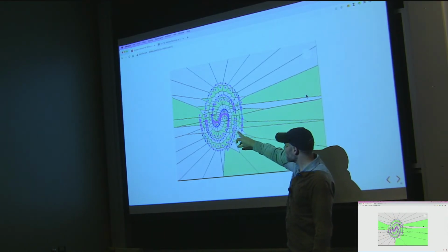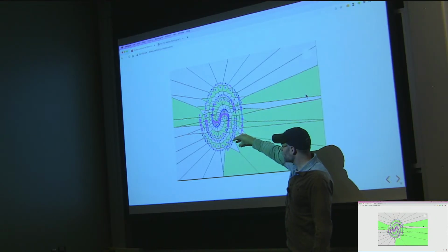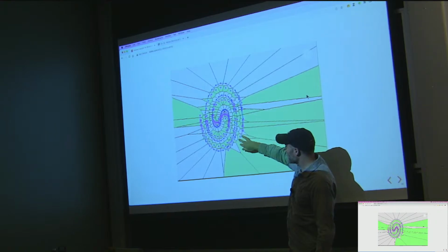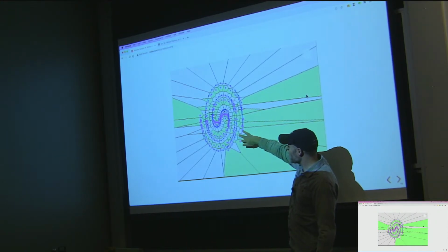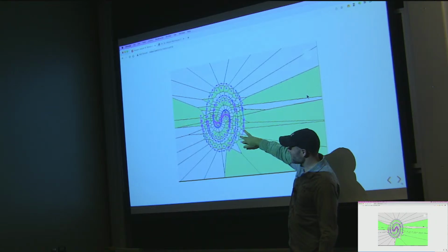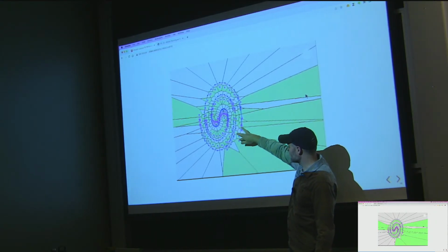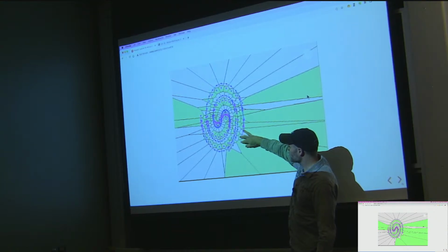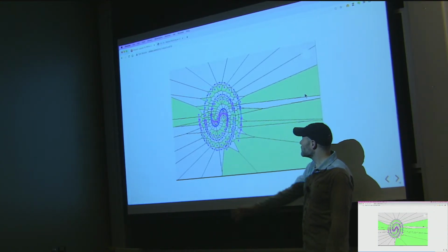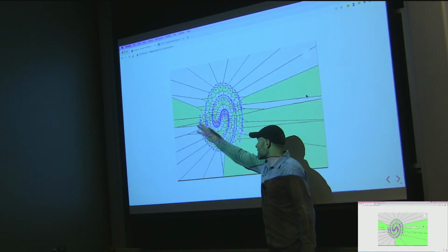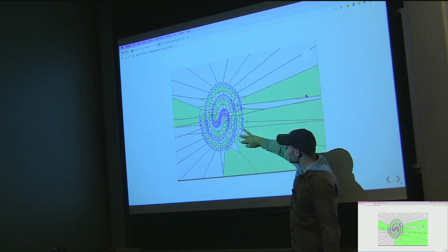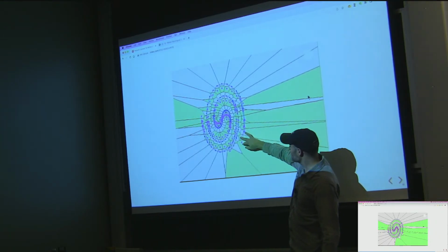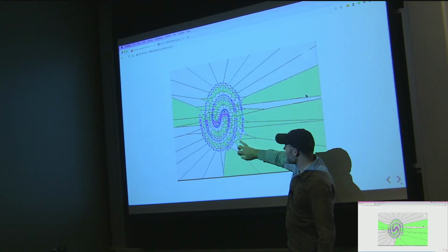Every time I add a node to the tree, I'll cast out a few samples as if I were to hypothetically simulate this forward a few more times, and I get these pink nodes. I'm not going to add all those pink nodes immediately to the tree, because then I'd have this super dense tree fallen on itself. Instead, I'll keep those marked as separate. These are my reachable frontiers. And then when I do my random sample in the entire state space, if my reachability frontiers are closer than any point that's actually been added to the tree, then I'll accept that candidate.